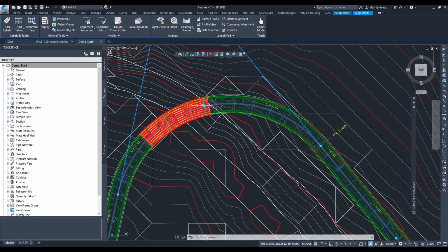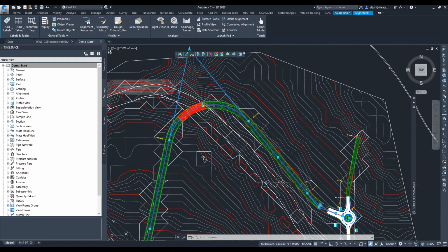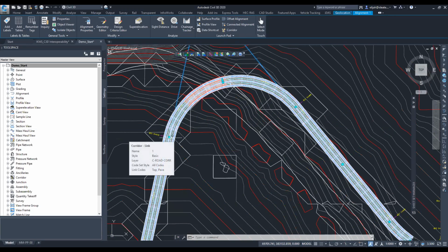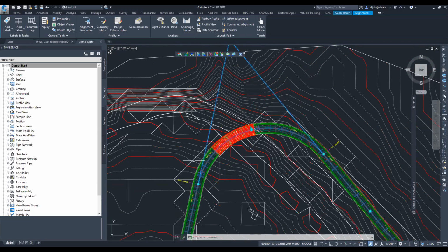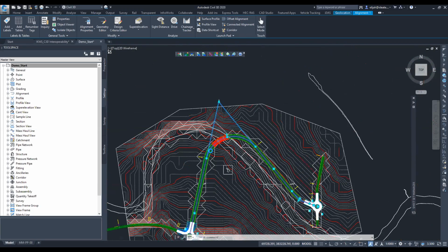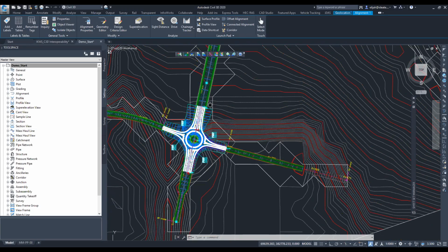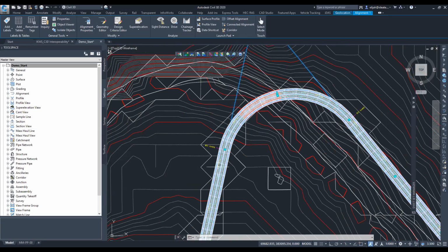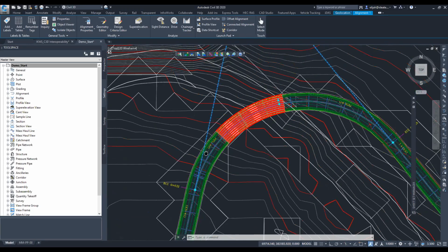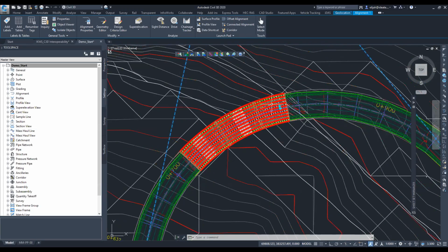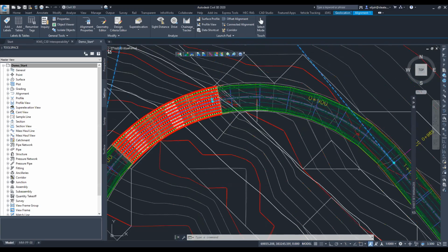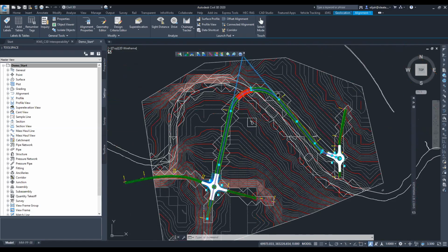So if designing and documenting that part, those are some of the design information that should be provided side by side with the operation of the road. If you approach this particular chainage, the design speed should be reduced from 100 to 50. So if you are approaching from the roundabout, going down straight at about 600 meters, you lower your speed just to ensure that you are safe and not toppled by the effect of centrifugal and centripetal force when negotiating that curve as well. So those are some of the details that you're able to achieve with Civil 3D.